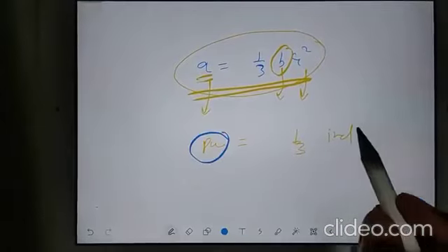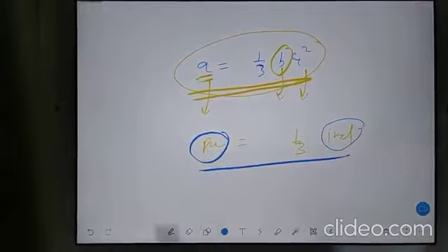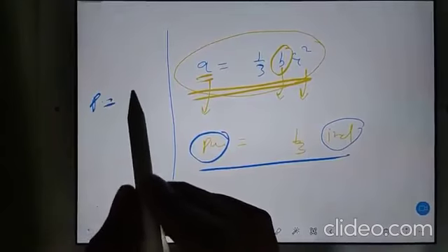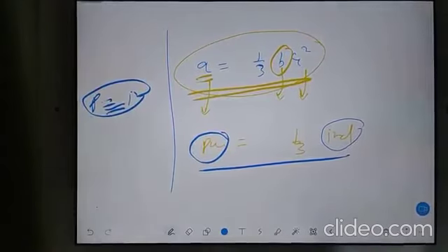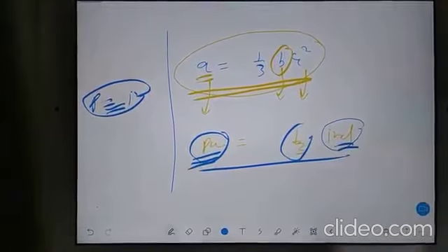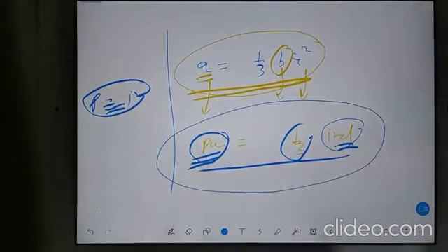So if you have achieved the relation between parasite drag and induced drag, see, in case of the minimum drag condition, parasite drag was exactly equal to induced drag, because they share the same coordinate. But here your parasite drag is 1/3 of induced drag. Now, how will you understand this physically on the graph?